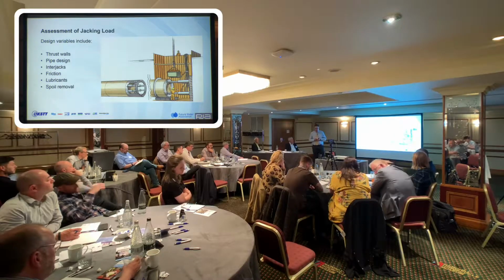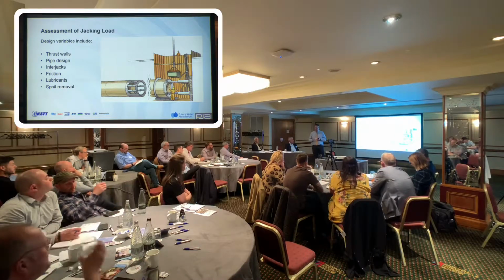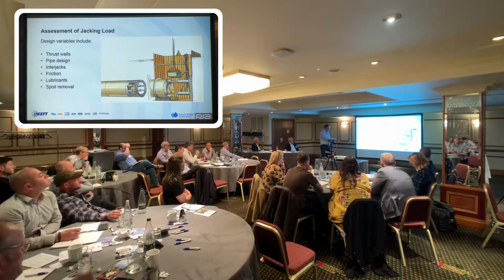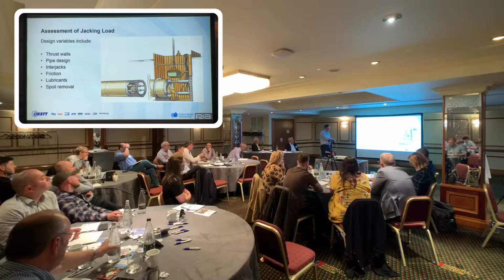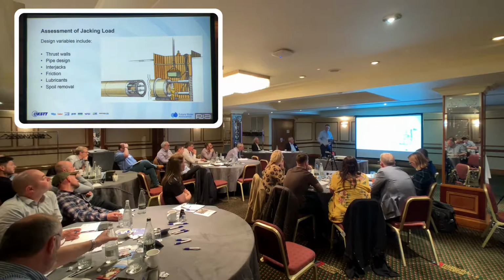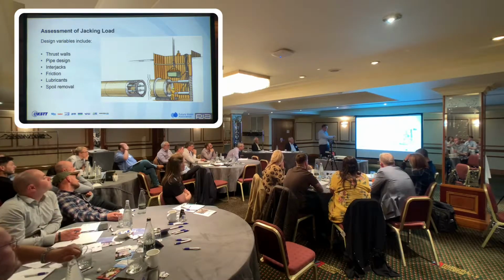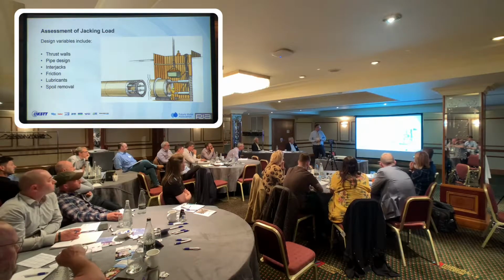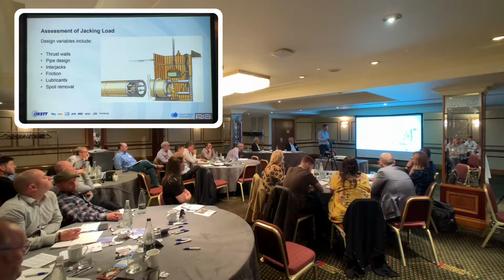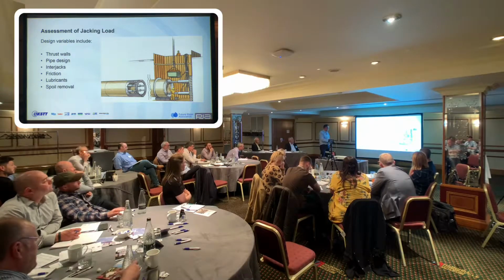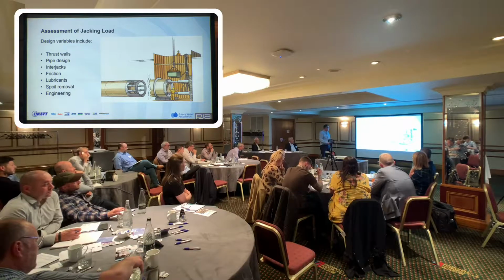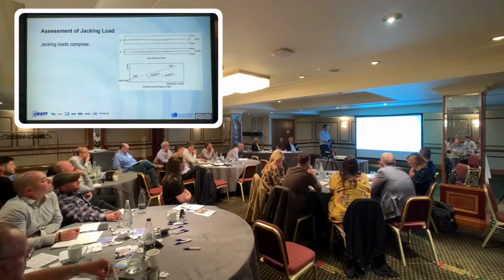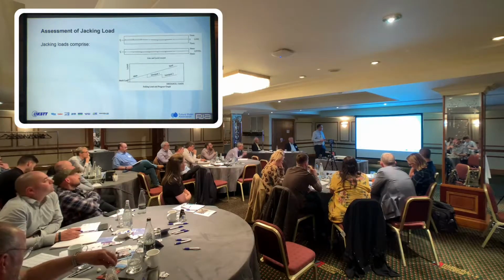And then also, people refer to it as face load or earth load. If this was the TBM, the tunnel boring machine at the front and the shield, you tend to get a bit of load from resistance on the cutting edge down the actual can itself, because you're not lubricating through that section, and then from the lead pipe. So there's three areas that you pick that load up from. But the specific type of engineering that you're looking at can affect the loads.